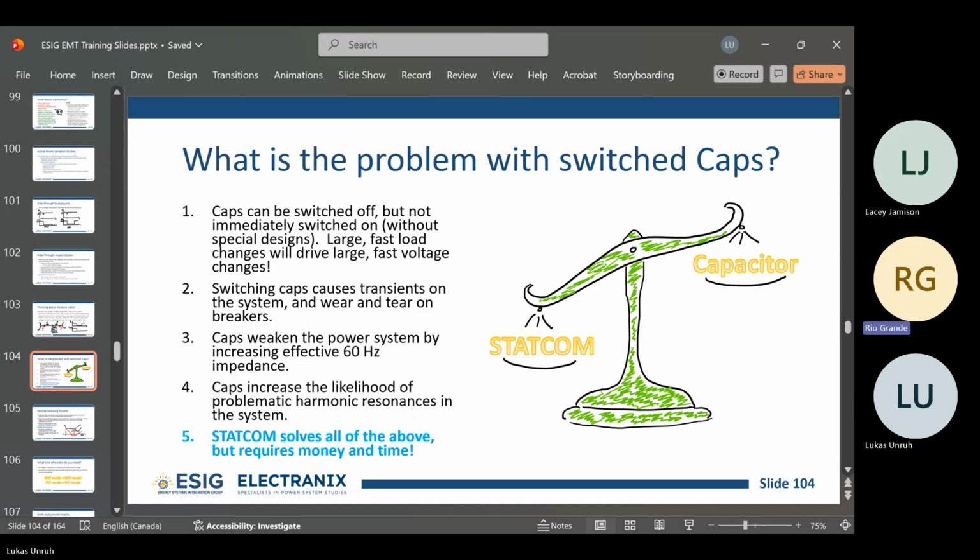Is another approach to maybe solving this issue as you've presented it would be to slow down their reconnect ramp rate after tripping? To basically say if you disconnect for whatever reason, you can only reconnect over such a ramp rate. Yeah, that can definitely be a solution. The SVC or STATCOM is just so expensive. Yeah, and there's a lot of resistance to them. Yeah, I mean, it kind of depends on what the specific problem is. If it's frequency, then you probably want to come back up as soon as possible. But if your system can handle it, coming back slow is probably going to be better.